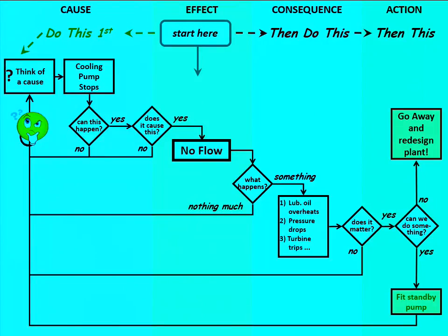And then we have to say to ourselves, does it matter? Sounds like a trivial question, but does it matter that the turbine overheats and stops? Well, it does. Sometimes you'll get to this stage and you'll say, no, it doesn't. You write that down in your log sheet, your template for the hazards, and continue. But if it does matter, the last question in the list there is, can we do something? And that's where the engineers sit round and they say, well, can we do something about this? And again, it depends on the plant that you're doing the hazard study on.